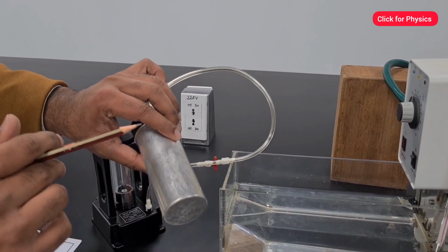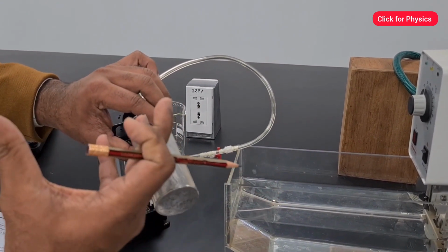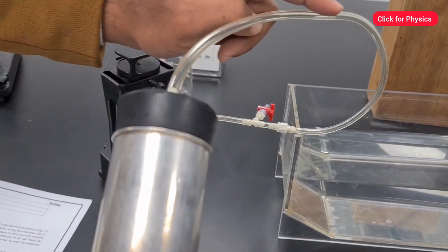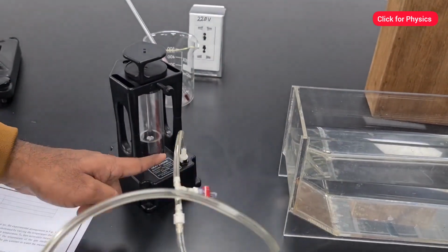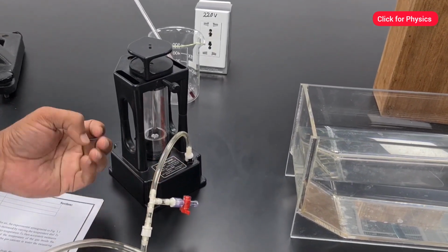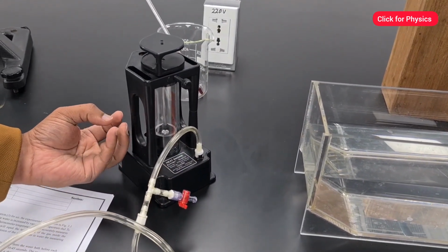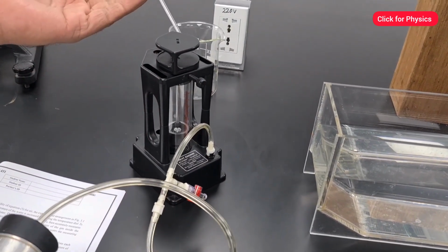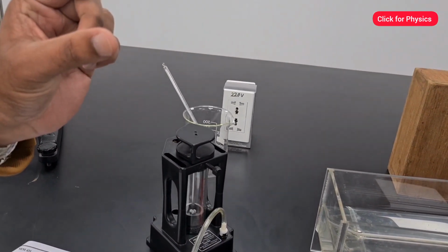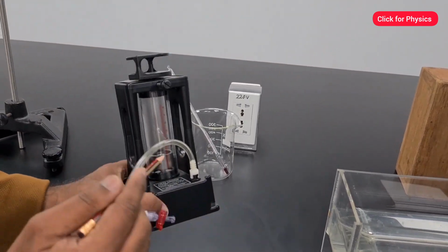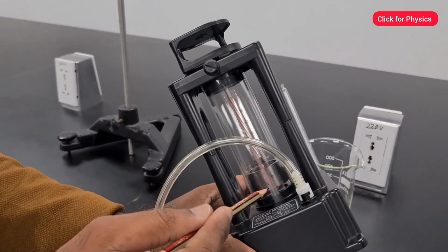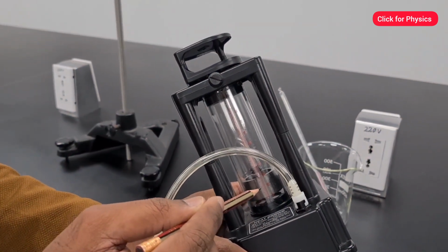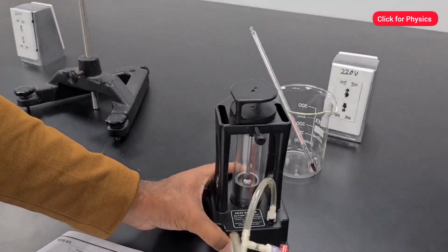Inside the canister you have a gas molecule. The gas will expand when you subject it to some temperature. What will happen? The gas will be passed through this tube. When it enters this calibrated measuring cylinder, it will push the piston upward. That means for every temperature there will be a change in the position of the piston. You can see here, for every temperature the piston will be moving up, so you can find the L value from the cylinder. Okay, so these are all the apparatus we are going to use today.